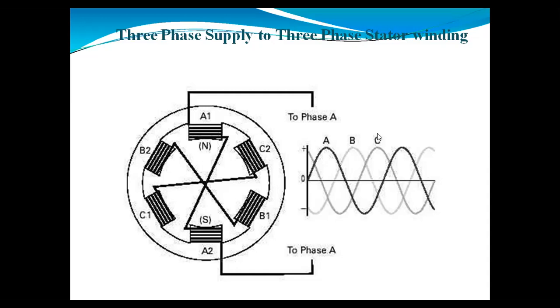And what we are saying, when we are supposed to use three-phase supply, at that time we will require the magnitudes of all these voltages to be equal. So 360 divided by 3, you will get 120 degrees for each. So you can give the voltage for each phase with 120 degrees. And if you see two adjacent phases like R and Y, or Y and B, the phase difference between these two adjacent phases will be 120 degrees.